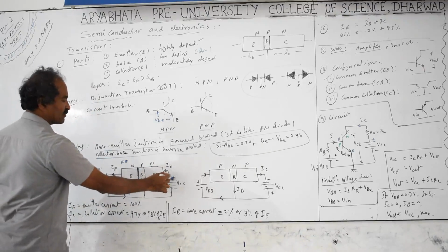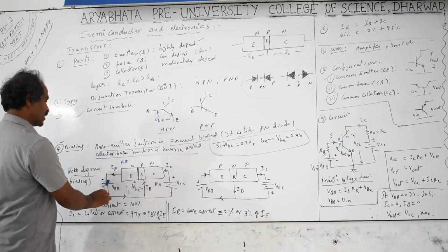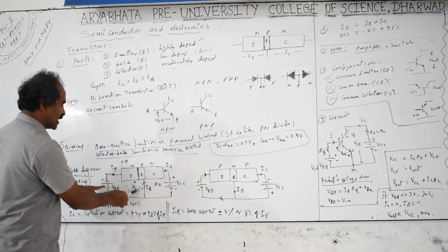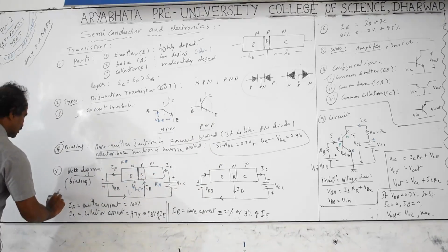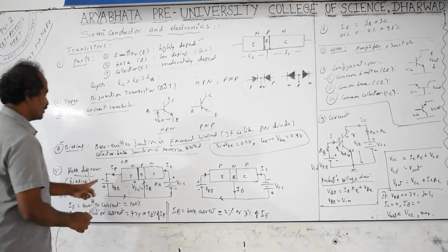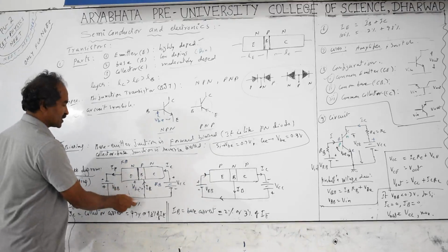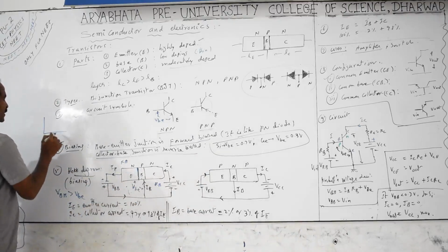Here more voltage means more current, but reverse bias current will not be there initially. Whenever VBB is more than VBE, for the current to pass, the voltage VBB, which stands for base bias voltage, should be greater than VBE, more than 0.7 volts. Then only the voltage overcomes the barrier and current passes through. This is just like a forward bias of the diode.